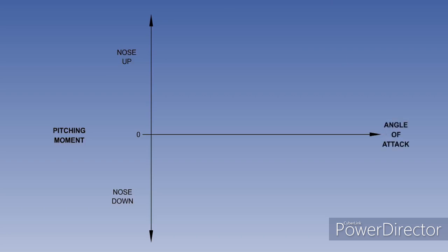Your previous knowledge will tell you that the horizontal axis could instead be labelled angle of attack or decreasing indicated airspeed. As you will see, all three values need to be considered to give a full understanding of these graphs. For the time being, we will use lift coefficient for the horizontal axis, but you need to keep the two alternative values in mind.